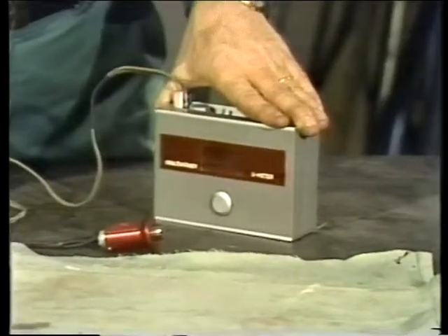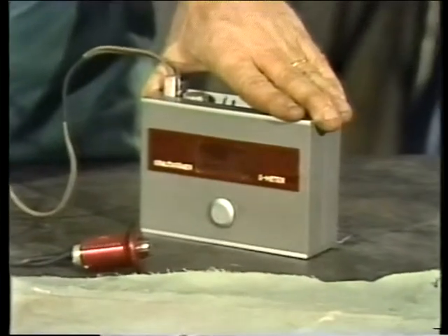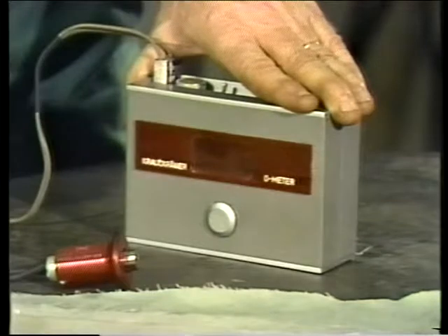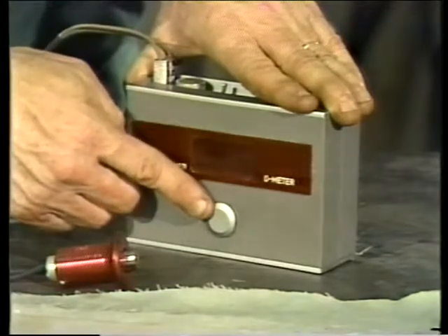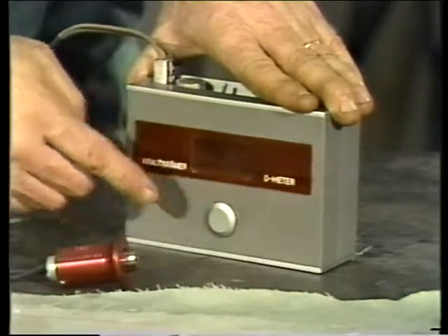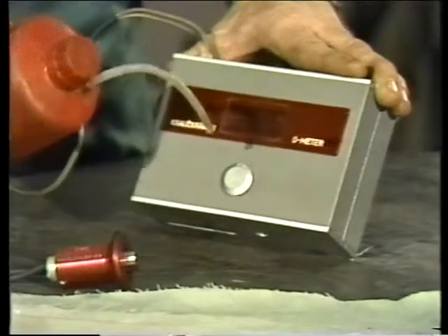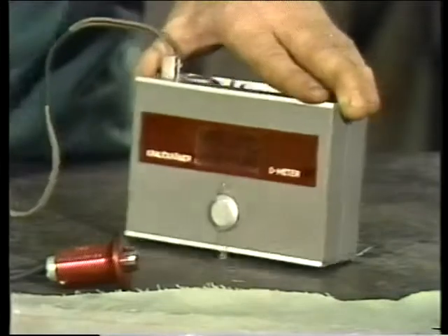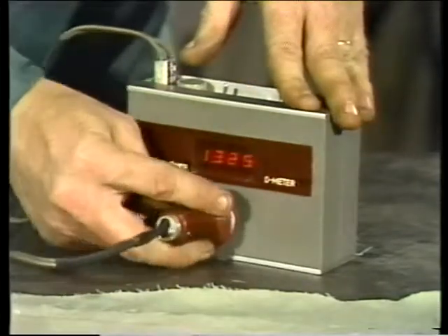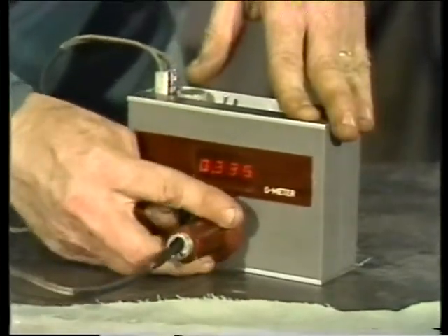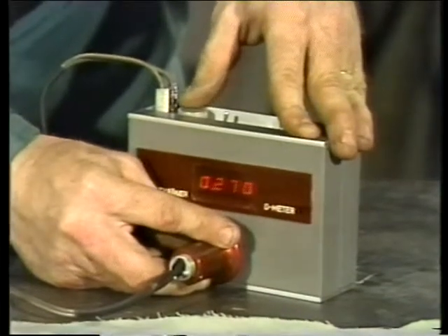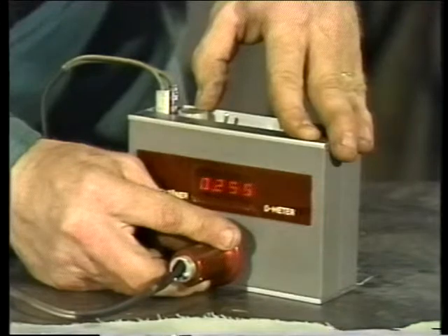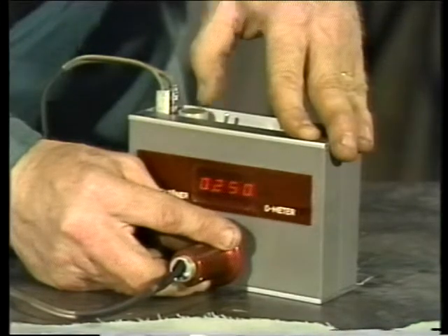This is an ultrasonic thickness gauge. You may be using it on the job to check the thickness of parts like boiler tubes. The thickness gauge is calibrated against the known thickness at this pad on the front of this meter. It's 250 thousandths. To calibrate the ultrasonic thickness gauge, put a drop of couplant on the pad and then firmly press the transducer against the metal. And then adjust this knob until the readout shows 0.250. The meter will now give an accurate thickness measurement.